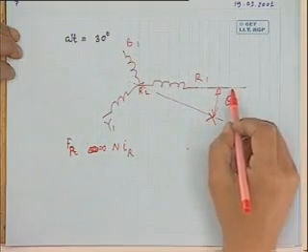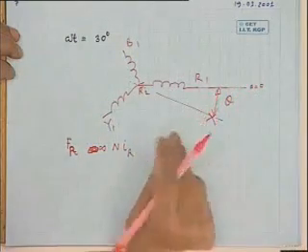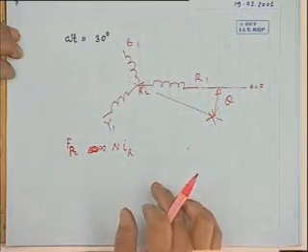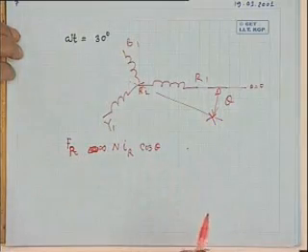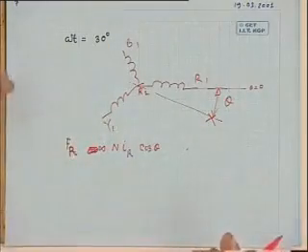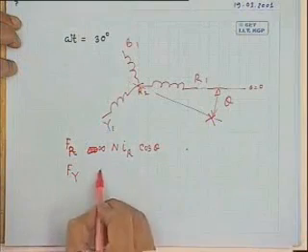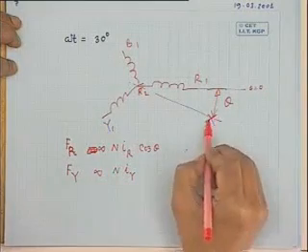And what should I write here? Suppose I take the reference of the maximum value of the MMF produced by A phase as theta equal to 0, then with respect to theta, what should I write? Cos or sin? Cos I should write. Suppose the axis of R phase is my reference for space angle measurement. So with cos theta it will be varying like this.